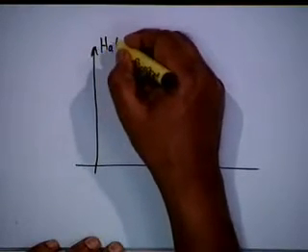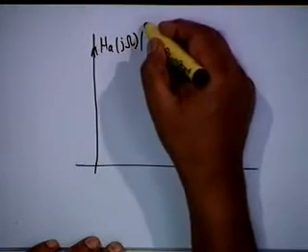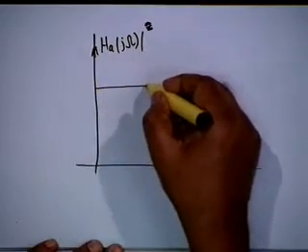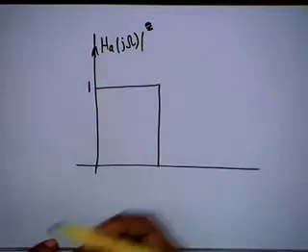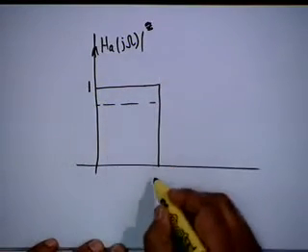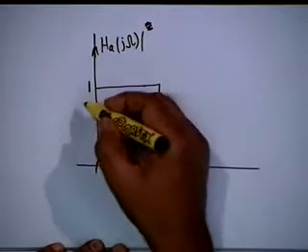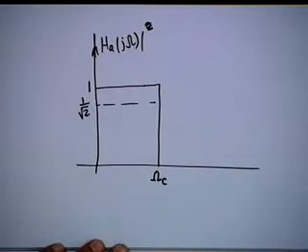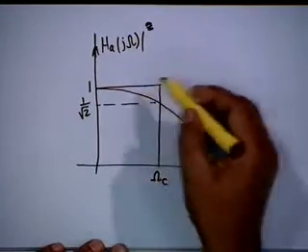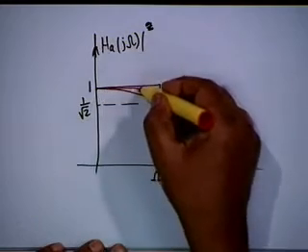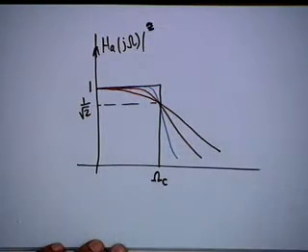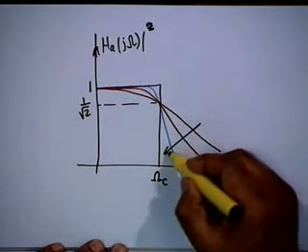And therefore if we plot H sub a j omega magnitude, let us plot the magnitude, then the ideal is this 1, and the value at omega c shall be equal to 1 over root 2 irrespective of the value of n, and therefore if we plot for various values of n, we will get plots like this, where capital N is increasing in this direction.